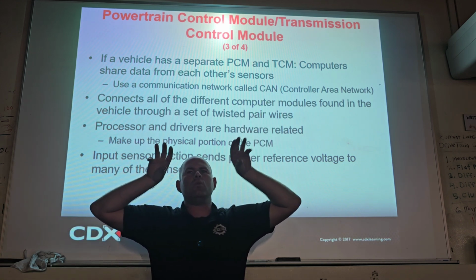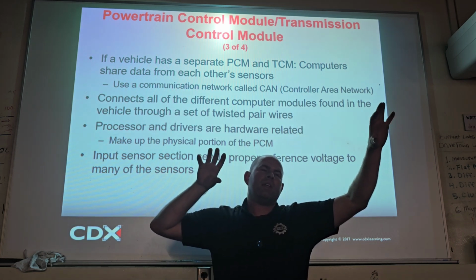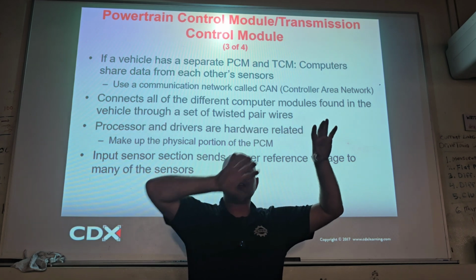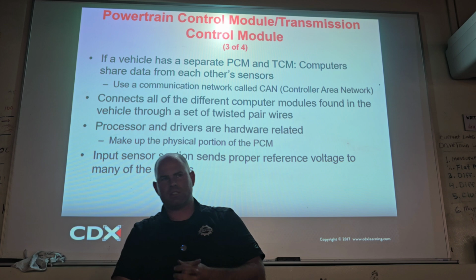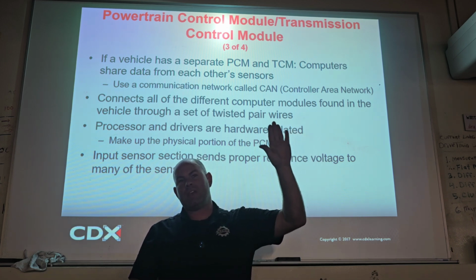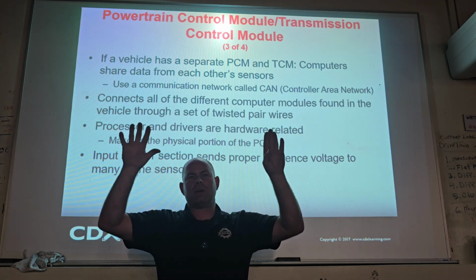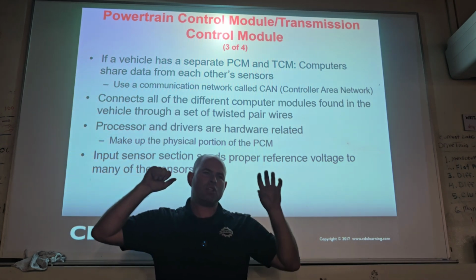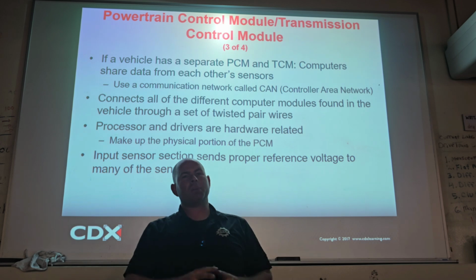Cool. So if you have a problem with a sensor that's over here in the ECM, the transmission can still get access to that information, right? So sometimes you might have diagrams with other modules on it. I'll give you a really clean example. Vehicle speed, a lot of times goes to the ABS module. Then the ABS module will use CAN high and low to get over to the TCM. If you got on a scan tool and you hooked it up and it had no communication with the ABS module, that TCM will probably not upshift.